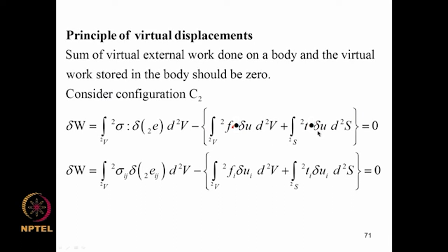So, that is how we developed nonlinear problems. In nonlinear problems, we recognize that if a structure is carrying a particular load P, we cannot apply the entire load in one stroke. So, we divide the load 0 to P into small increments, and we trace the solution as the load is incremented by small amounts. During an increment of a load, we can linearize certain system behavior, and that helped us to formulate the complete finite element procedure to deal with these problems.